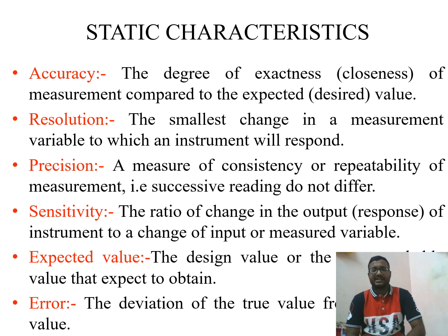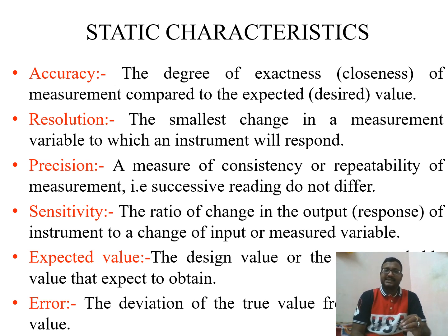And coming to the resolution, what is meant by resolution? Resolution is a small change in the measurement variable. That means if a non-zero input quantity is slowly increased, but the output does not change until some minimum change in the input takes place, that minimum change is called resolution. Simply, it is the smallest change in a measurement variable to which an instrument will respond.